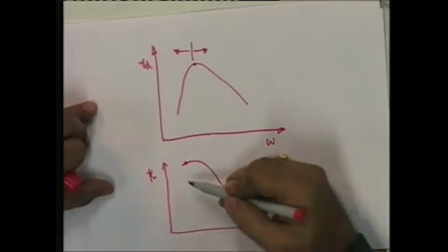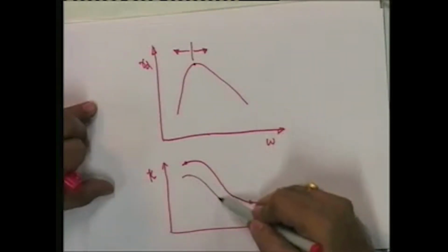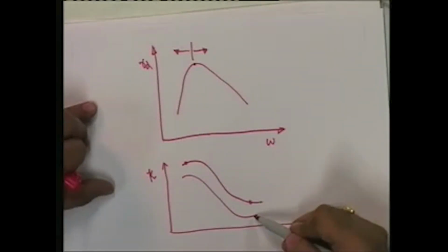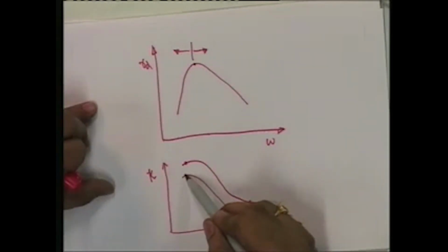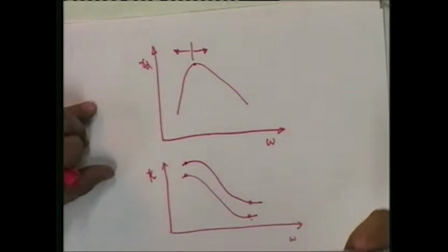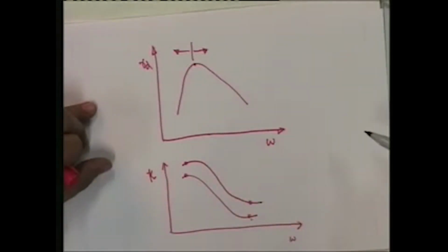Similarly, if I take this for a modified compaction, this is for a standard Proctor compaction. With a modified compaction it can have a value slightly less compared to this standard Proctor compaction. So, the increase in compactive effort decreases the coefficient of permeability. Here again we connect back to the type of the soil structure which is prevailing in that moist compacted state for a given soil.